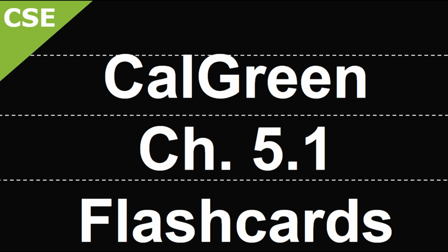Updated as of July 2024 code, it provides a table for electric vehicle charging station power allocation to determine the total power in kilovolt amps required based on the total number of actual parking spaces. The first requirement is use any kilovolt amp combo of EV-capable spaces, low power level 2, or DCFC EVSEs, and at least 1 level 2 EVSE shall be provided.